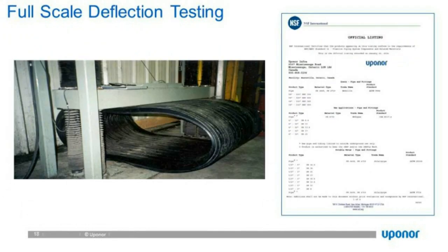The design requirements for pipe manufactured to ASTM F894 standard are quite stringent. For example, this photo illustrates the ASTM F894 flattening test, or parallel plate test, for qualification to the F894 standard. The pipe must be flattened to 40% of its ID. It has to show no splitting, cracking, breaking, or separation of the pipe walls or bracing profiles.